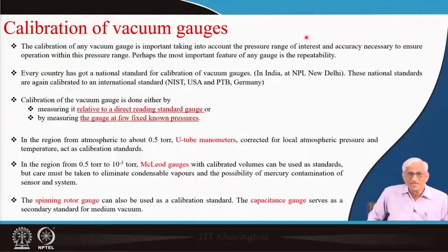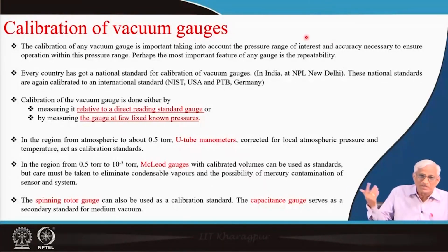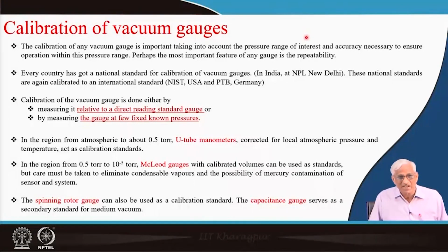That is important. If you make one mistake, 10 power minus 5 will be measured as 10 power minus 3. Then, instead of a semiconductor, you will get some other insulator, oxidized. Silicon, for example, when you are processing under vacuum, it will be silicon. If you are processing under atmosphere, it will be silicon dioxide, which is sand. It is no more a semiconductor, it is an insulator.